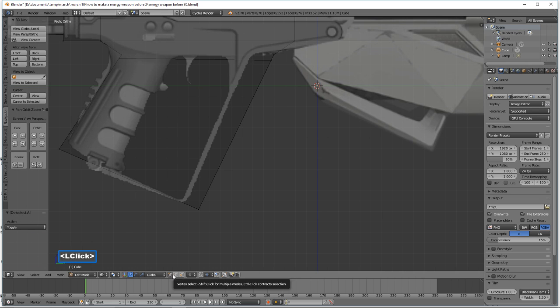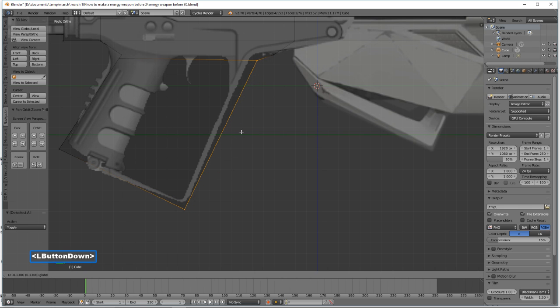I'm going to click here to go to vertice select. I'm going to make sure we're on vertice select. I'm going to hold Control as well as hold the right mouse button. I'm then going to draw a lasso select around these 4 vertices. It looks like 2 vertices, but it's actually 4. And then I'm just going to take the manipulator and push over like this.